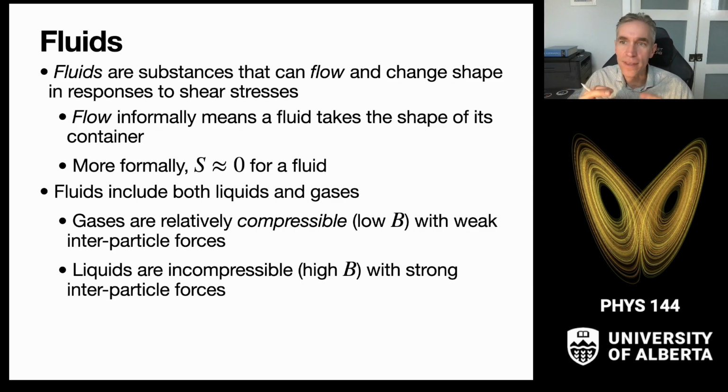More formally, we think about this as having a near zero shear modulus, and similarly the Young's moduli of these are also close to zero. They can have large bulk moduli, but the shear and Young's moduli of fluids are low, because if you press them, like give them a tensile compression, or you try to cause them to shear, they'll just move without much resistance.